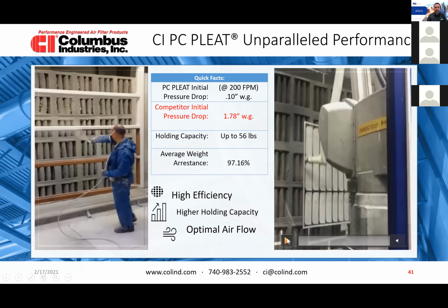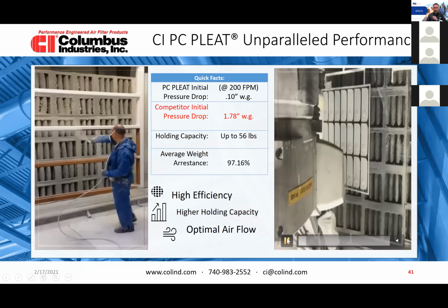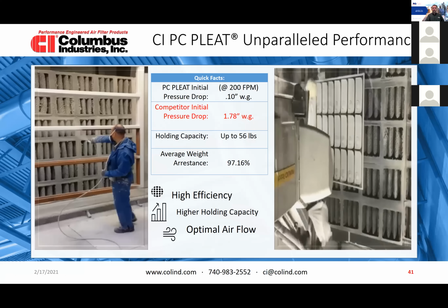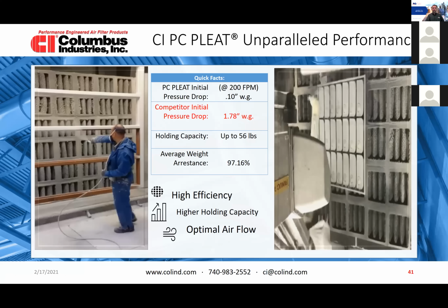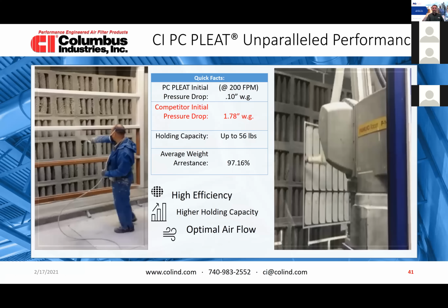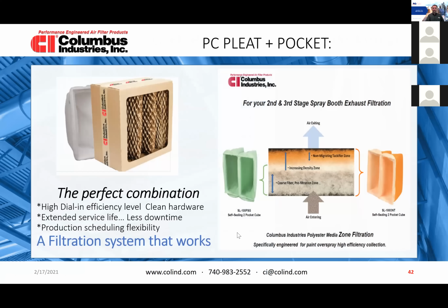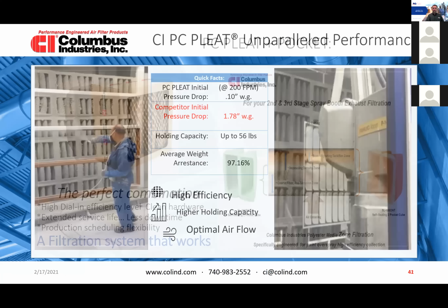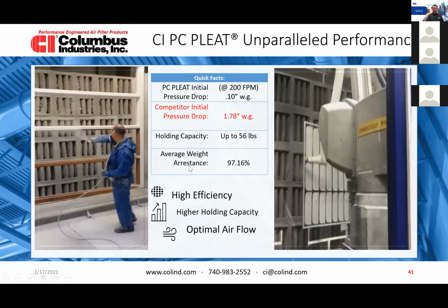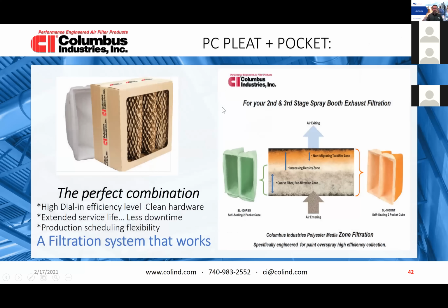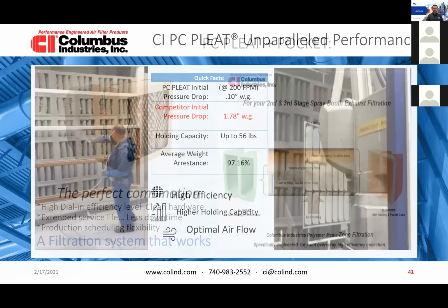This is an automatic or robotic application. Again, the filters are behind, and as you can see, they're not too far behind. Okay, now, again, it's moving on me. I'm sorry about this. This is the first time I use the application here. The quick facts that we talked about before, at 200 feet per minute: 0.1 versus as high as 1.78 inches of water.